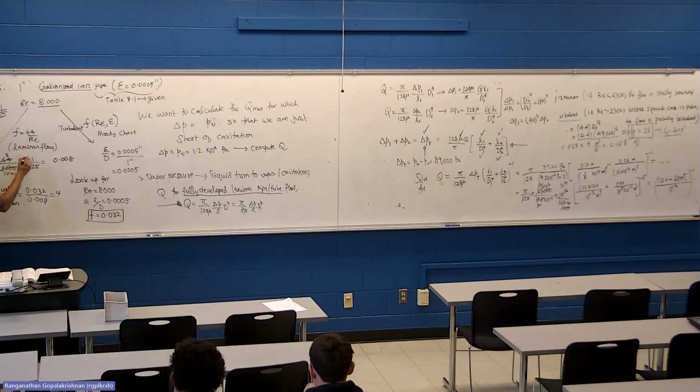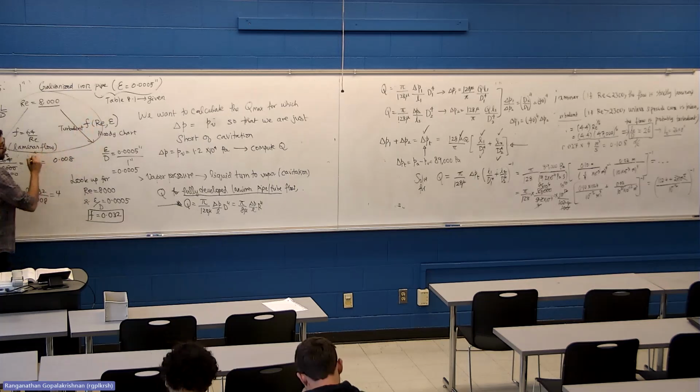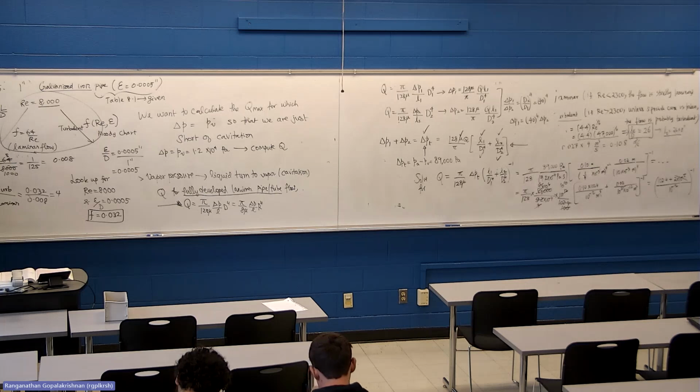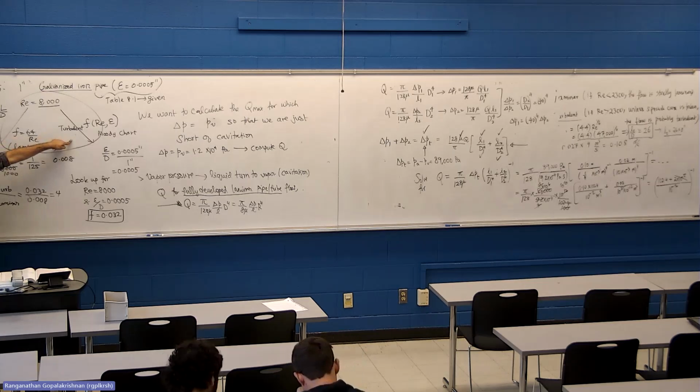So getting this decision right is crucial for two reasons. One is turbulent flow on average will always have higher pressure loss than laminar flow. If you mistakenly think a flow is laminar when it's turbulent, you are massively underestimating the pressure drop, which can have serious consequences on how much pressure drop you calculate and what pump you select for your particular application.